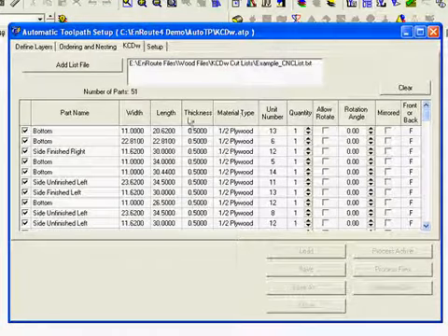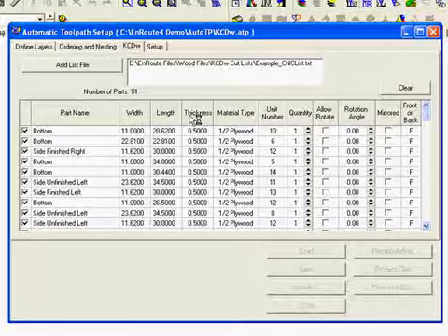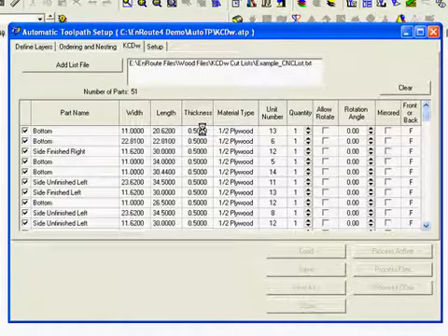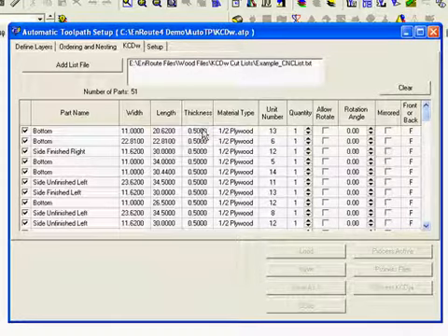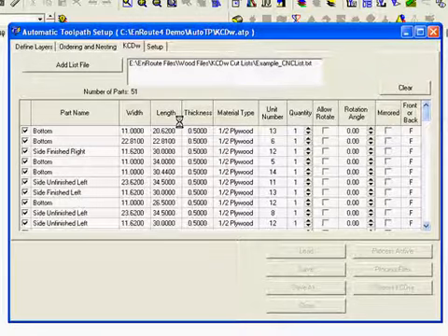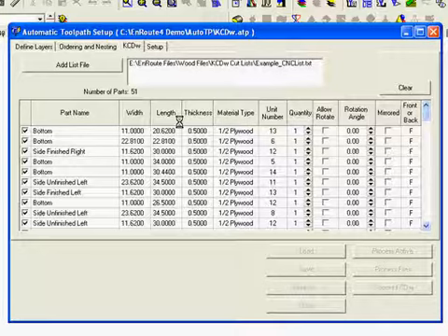And we take into account this thickness when creating output files. So for instance, if you're surfacing at the bottom of the plate or surfacing at the top of the plate, with these values, your end cut thickness will be correct. And in the case of the bottom of the plate, this specific material thickness is used when determining how much above 0 the part needs to go. So it's an important variable when surfacing on bottom of plate. So once we're done here, we'll have the output files, the layer printouts, and an Enroute file that will allow us to go in there and make changes if needed after this process has been done.